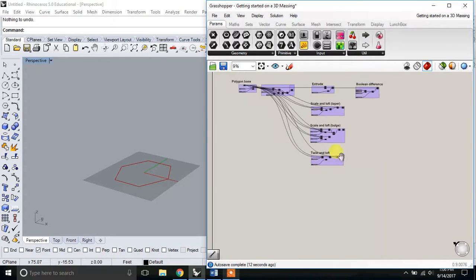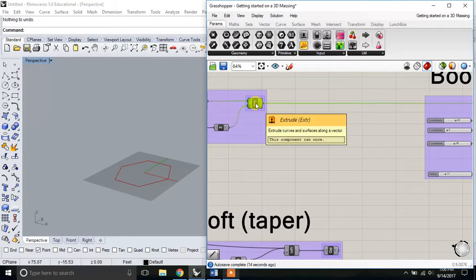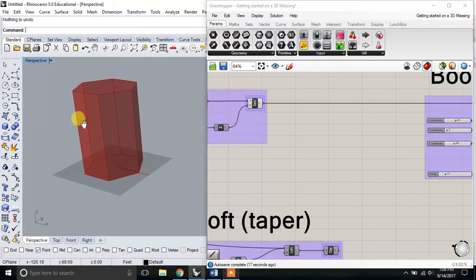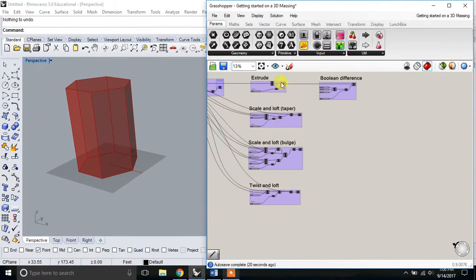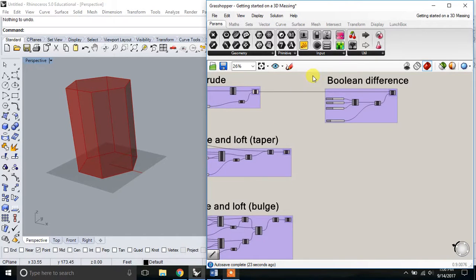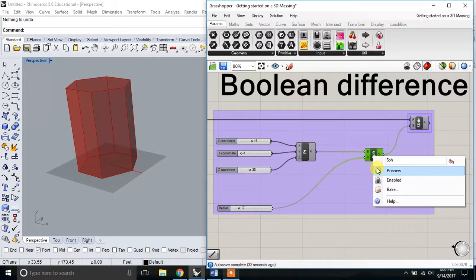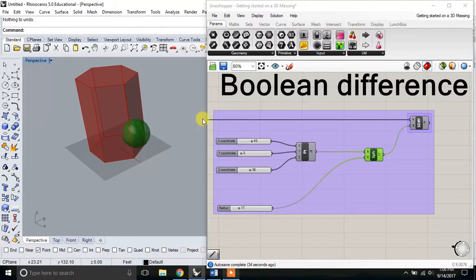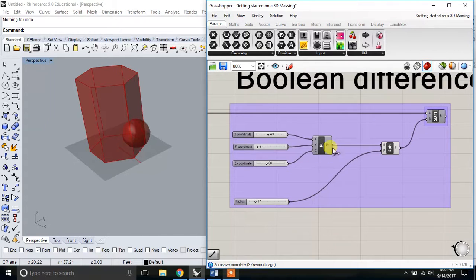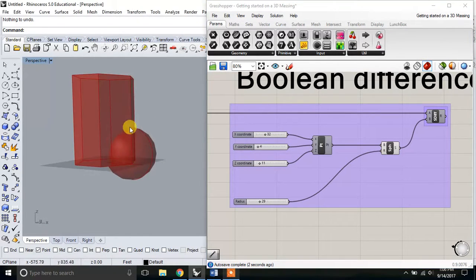So then, just as a quick example of some even more complicated geometry, we can think about any of these methods being plugged into the Boolean operations. So for this one, I'm just making a really quick sphere. The sphere wants a center point and a radius, so that is adjustable. I can move the sphere around, make it larger, smaller, higher, really locate it wherever I'd like it.